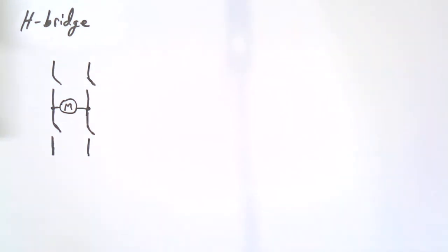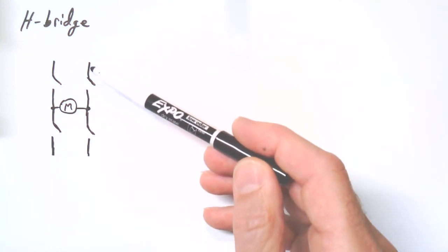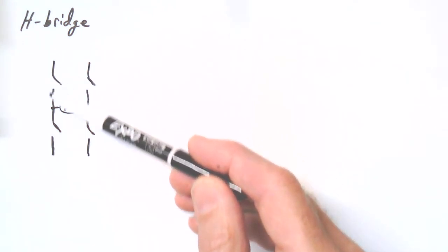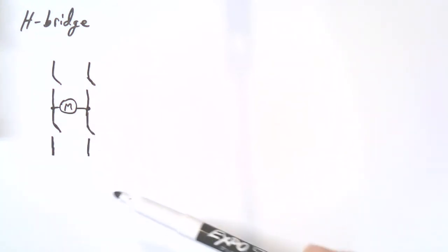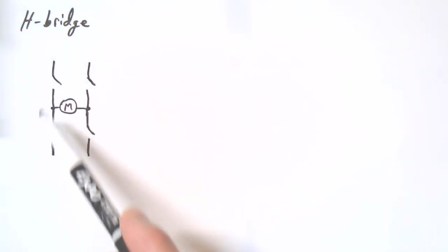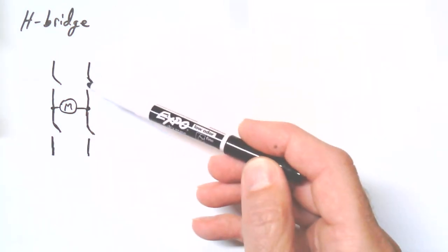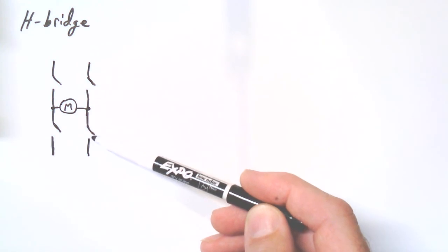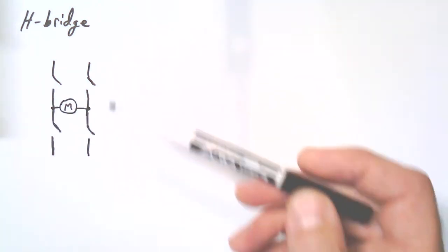The H-bridge, I think, gets its name from what's somewhat of an H shape. If you can see, maybe that's one side of the H, the other side right down the middle. And that's the H shape that is there because it employs 4 SPST switching devices or actions. I mean, these could be literally physical contacts or transistors.